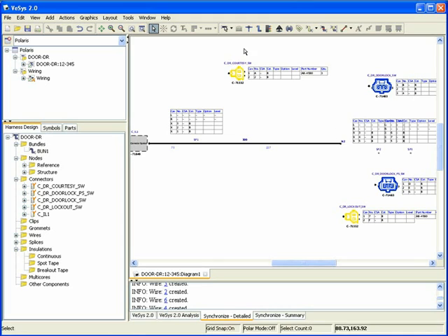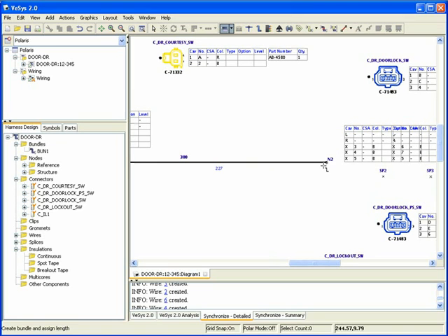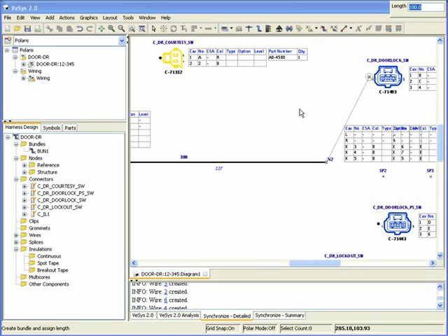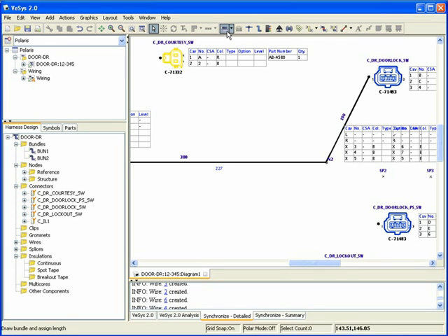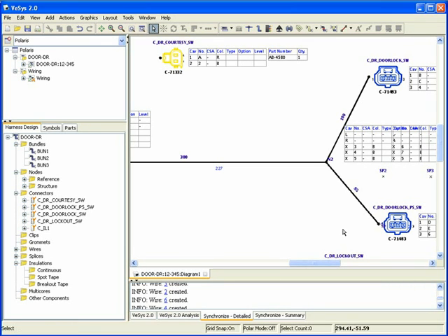We will use static bundles to connect each connector to the main bundle. These are unscaled, allowing you to define the length interactively, but in this case, we'll simply accept the default scaled values. For the rest of the connectors, we will time-lapse through, and where the node utility pops up, we will simply accept the default values provided.